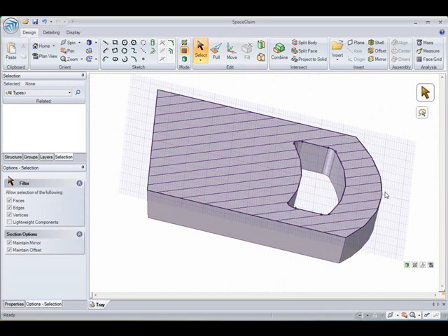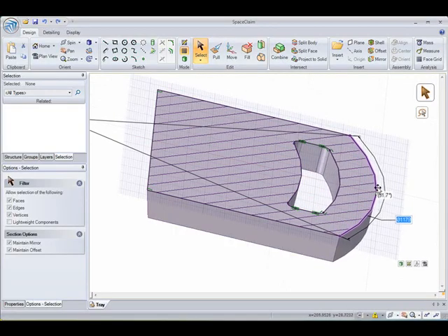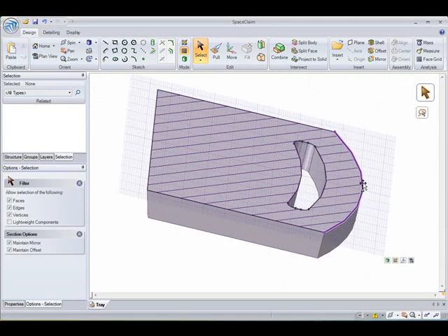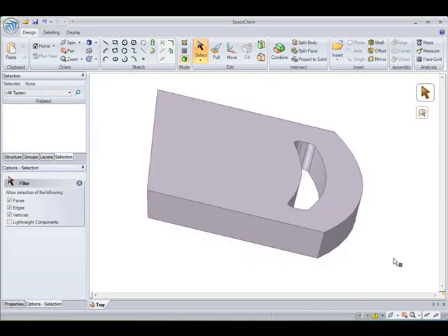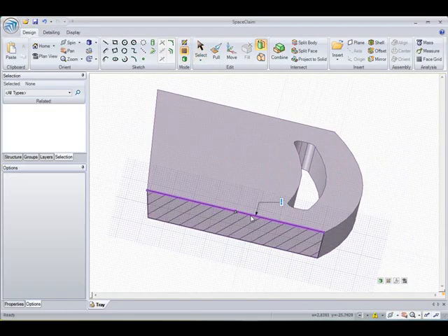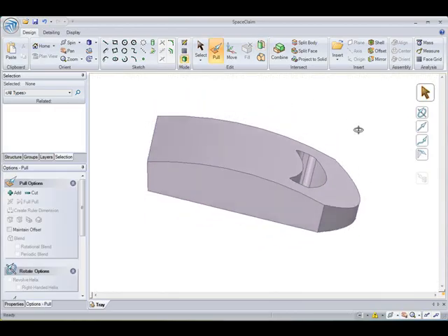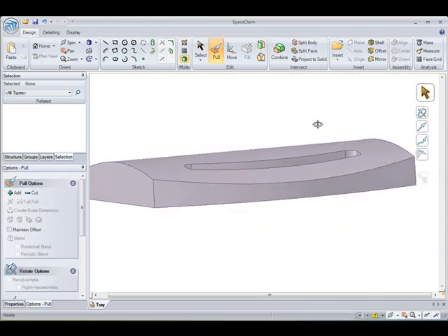But our grip seems a little bit big now, so I'll actually move this in the cross section and do a quick drag with select as I move this in. So I like the bend on the top, so I'll add another bend on the side by selecting the side wall as another plane. And I'll put another bend up, and 600's been working so far, so I'll add that in again. So I like how the bends look.